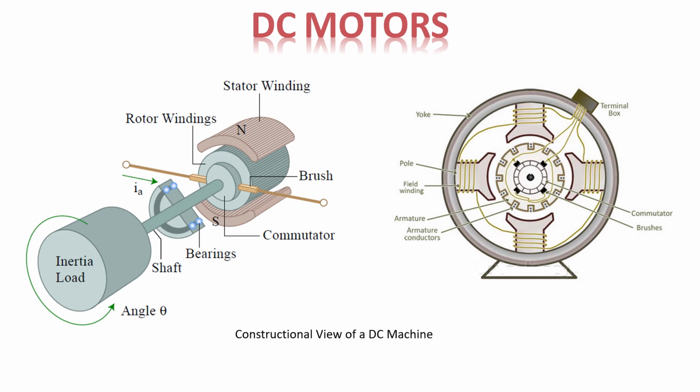Okay, let's see the first actuator, which is the DC motor. So the DC motor has the stator and rotor winding. When the voltage is given to the stator, it is energized, and automatically a current is induced in the rotor. So the rotor will also rotate, and since it is connected to a shaft, the shaft will rotate. To this shaft we can attach the link of the robot. So as the shaft rotates, the link will also rotate, or the joint will also rotate.